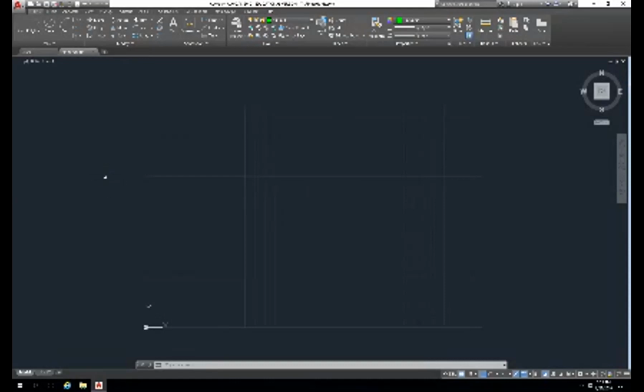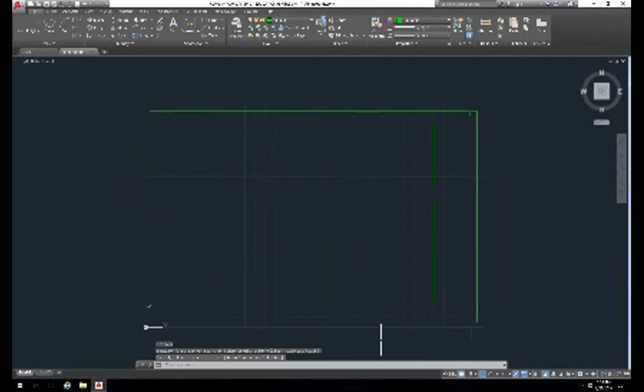So here I'm doing the ribbon. I'm doing the rectangle in the ribbon. What do we have? We have rectangular polygon. If I type the letter R, it'll start. So REC would give me rectangle. Press enter, and it says where's the first corner, where's the second corner, and we just draw a rectangle. Now, once we drew the rectangle, right now, this is one single object. If we click on it, you see it selects the whole object.